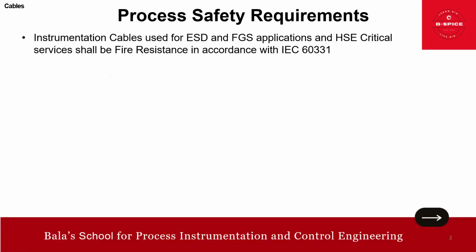Process safety, in the sense that the instrumentation cables used for ESD and FGS applications and HSE critical services shall be fire resistant in accordance with IEC 60331. We have already uploaded a video exclusively on the standards, and we are referring to this.